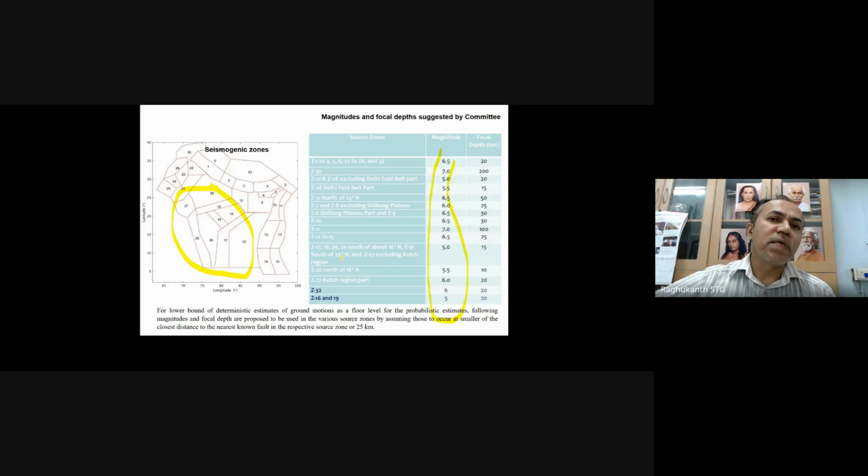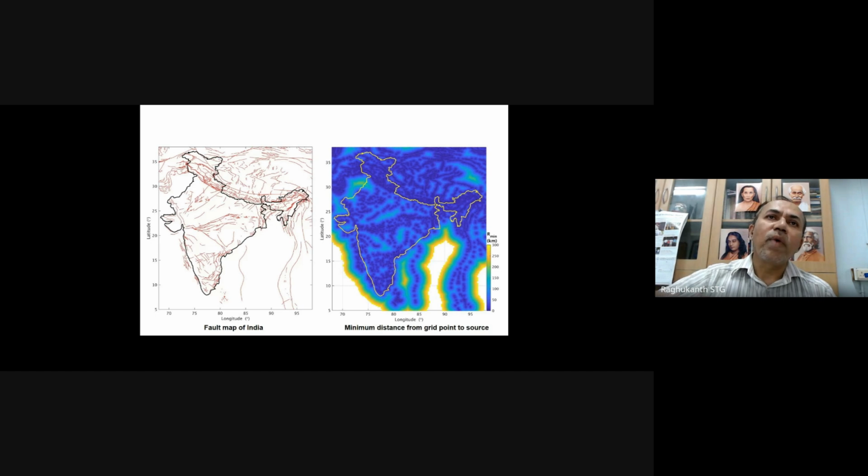So what we try to do is, for this also we estimate the ground motions actual, and this will be like a lower bound kind of thing for our analysis itself. Once again, you see the same fault map has been used, and these are the distances here. If the distance is more than 25, say, that will be recalculated to 25 itself. So we limit these numbers itself.